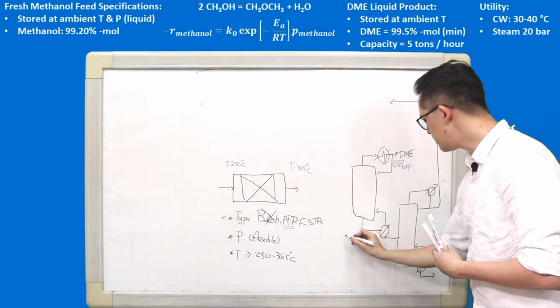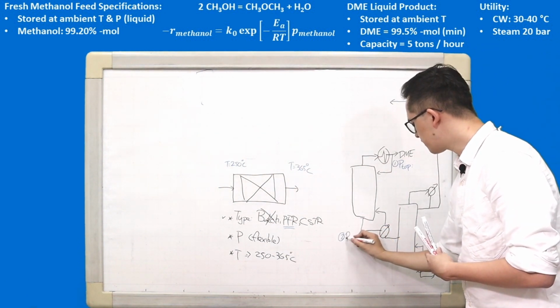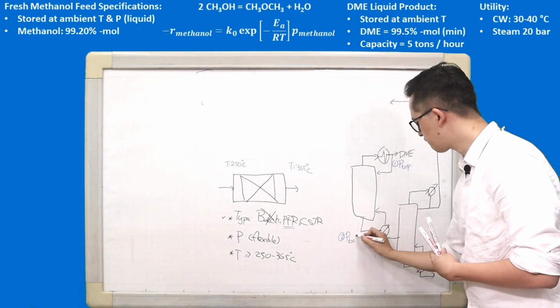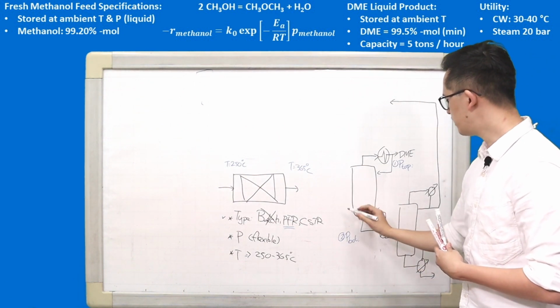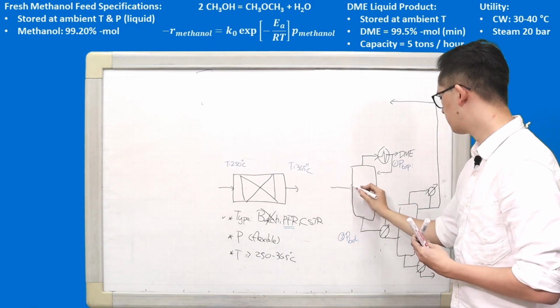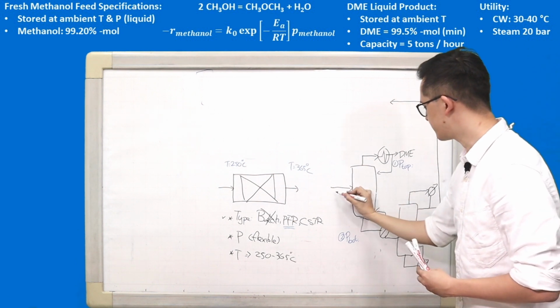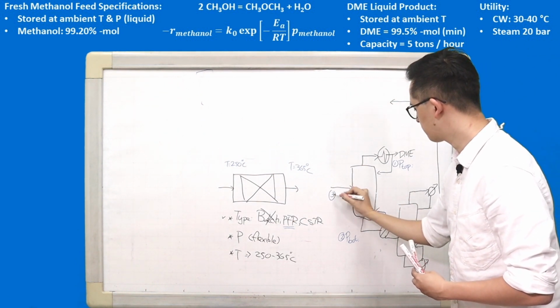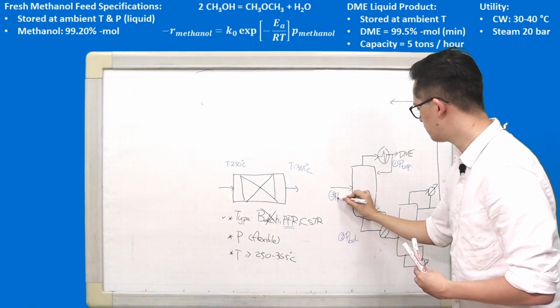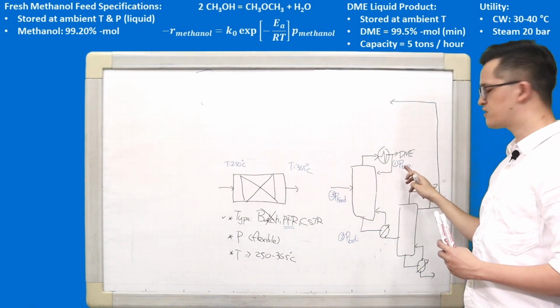Using those information, we will set the correct bottom pressure, and then later on we will define the feed pressure. That's the third step. Pressure of your feed. Okay, but again, it always starts from the top.